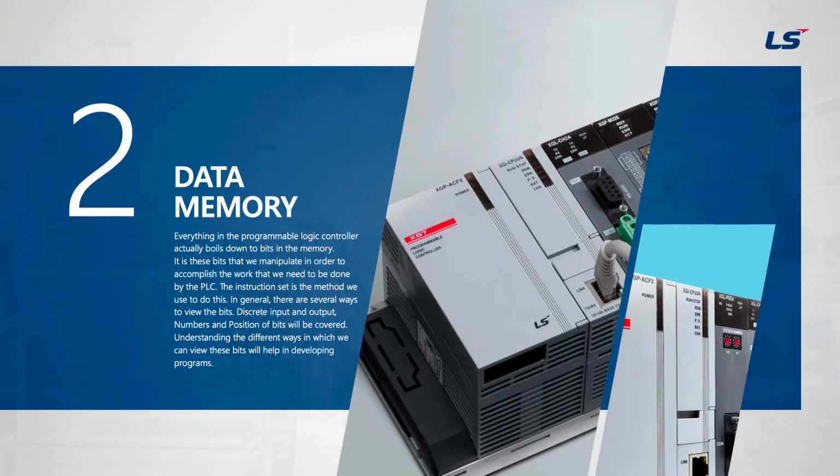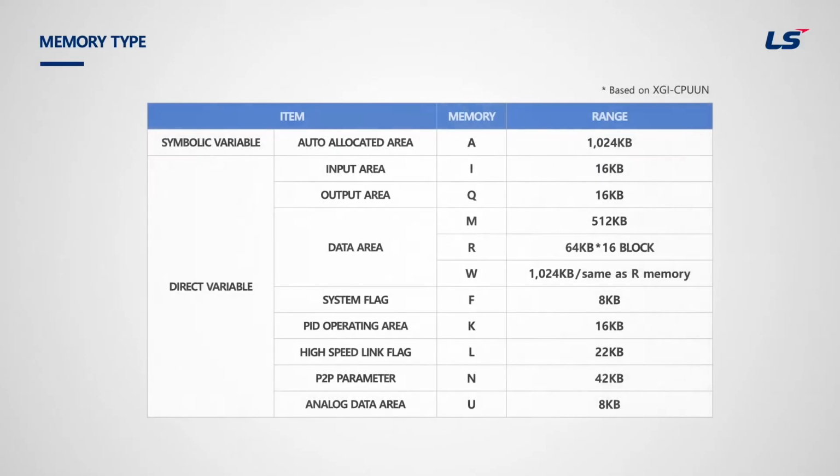In this chapter, we will take a look at PLC data memory. Here is the list of PLC data memory for XGI. The range is based on XGI CPU type. There are direct variables and symbolic variables.